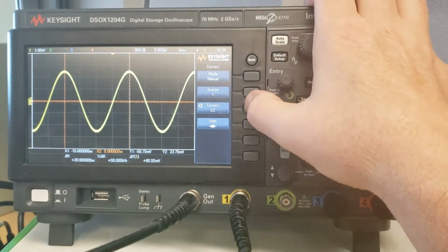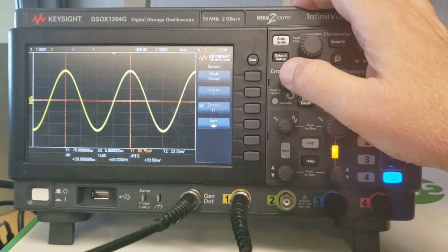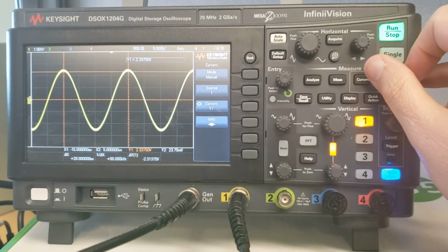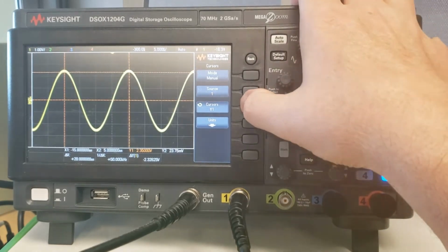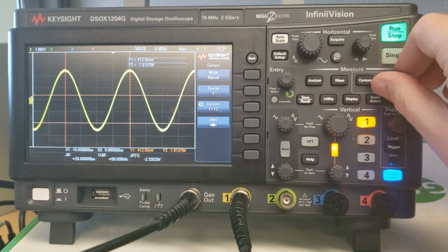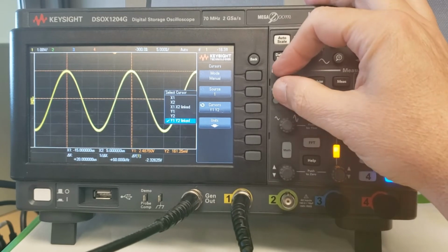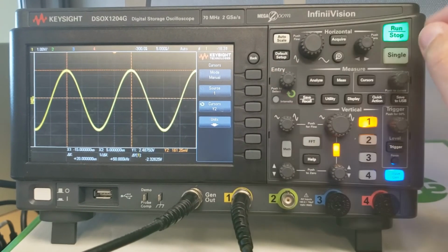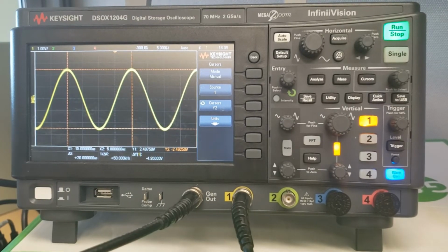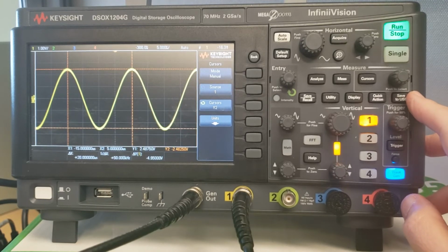I guess we wanted to have Y cursors. We go to Y1 and then hit this button to select it. So that's the Y1 cursor, and you can see that here. Bring it to the top of the waveform, and if I wanted to select Y2, just down here, and it looks like you can link them together. That's linked. I didn't really want that, so let's go to Y2 and then hit it to select. Now they're not linked. I can measure that. Okay. You can save to USB. I don't have anything connected there to try that out.